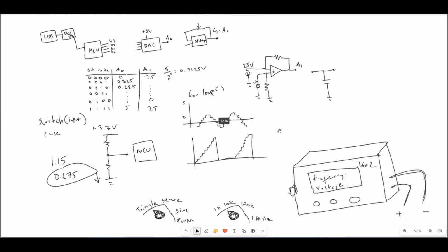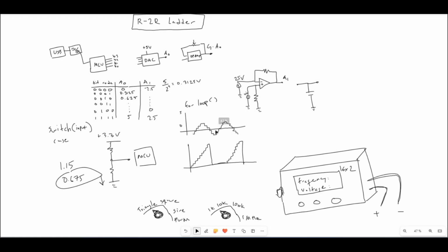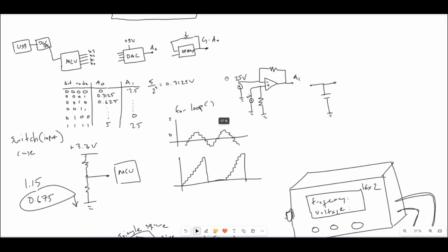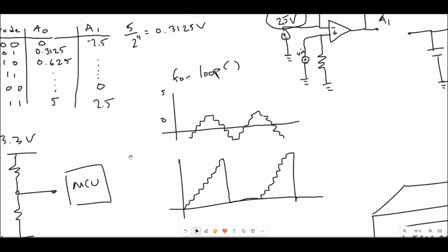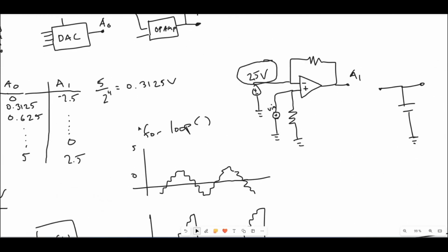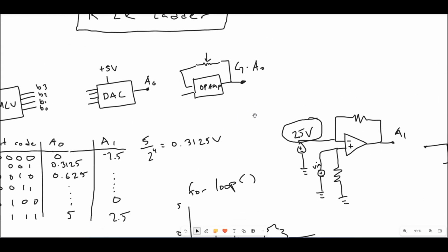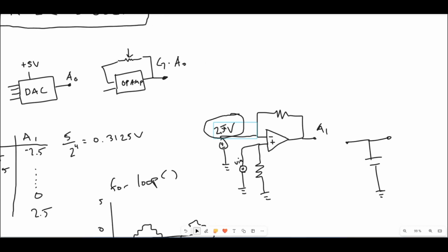Yeah, hopefully that gives you a brief overview of what a digital function generator looks like and how it would operate. I see there's a possibility here for an offset as well. So you can have this input here as a variable, its own dedicated voltage that you can use your MCU to produce. And this way, also with a knob and switch case in your MCU code, you can have a variable offset as well. We did not do that, but nothing stops you from doing that.